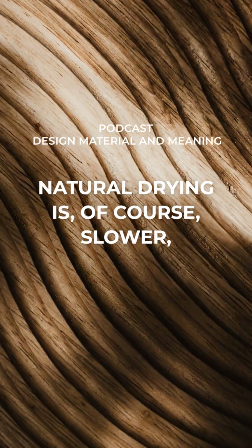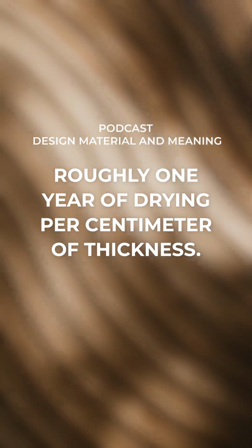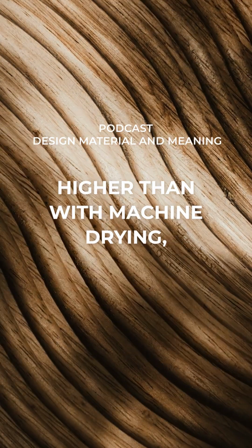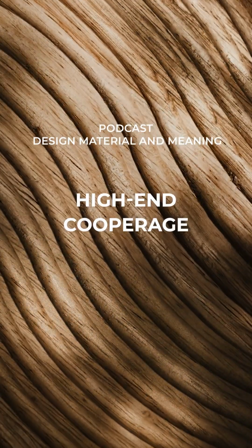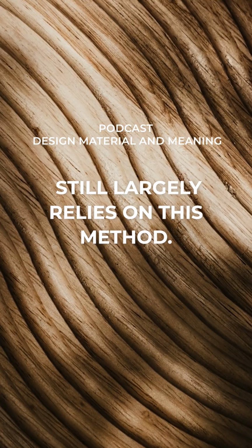Natural drying is, of course, slower, roughly 1 year of drying per centimeter of thickness. The final moisture level remains slightly higher than with machine drying, but the process is much less energy intensive for the planet. High-end joinery still largely relies on this method.